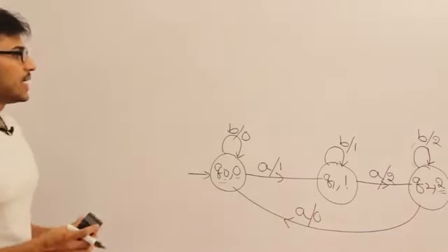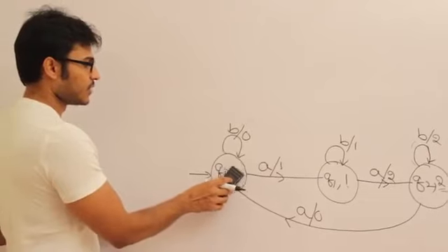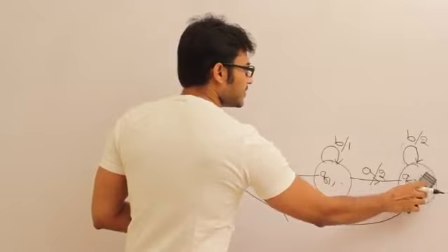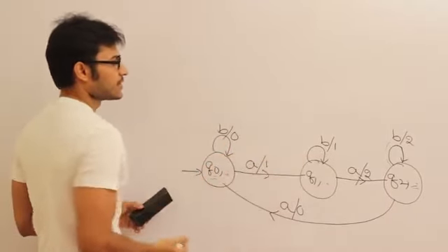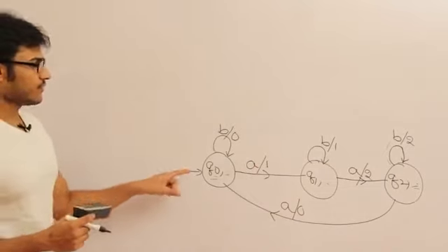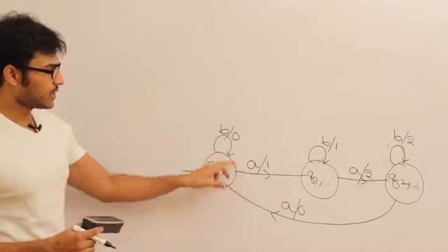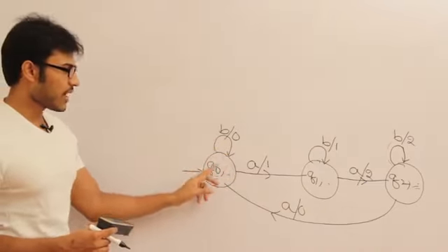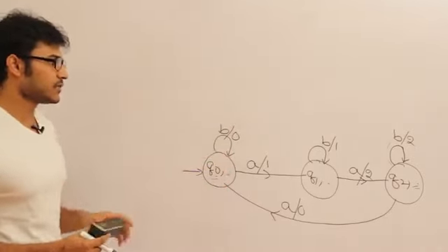So this is the Mealy machine. So you can simply remove this, and this is the Mealy machine. Now the output is associated with transitions rather than states. So how did I convert it? I have first finished the diagram for the Moore machine, and then I have taken each transition, and if a transition is going to some state, I'll take the output associated with that state and associate it with the transition.